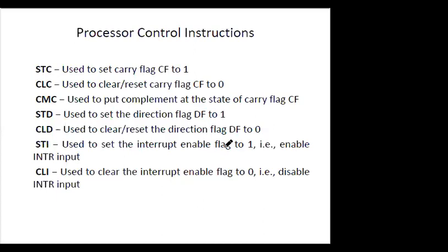So again, there is a bigger role to play by the flags. The flags are also controlling the process of the microprocessor. So process control is also being done by flag registers. Program execution transfer, branching, and loop is also being done by the status of the flag register. As I have mentioned earlier, the flags involve status manipulation.